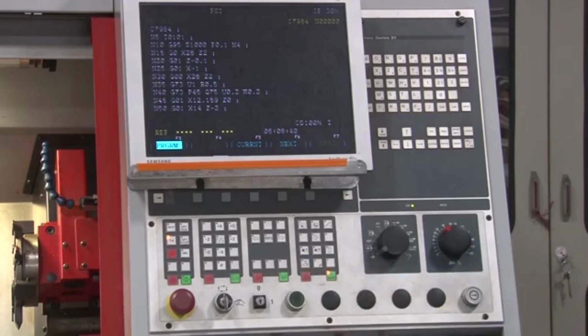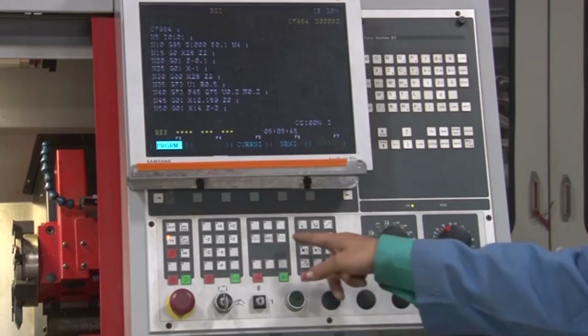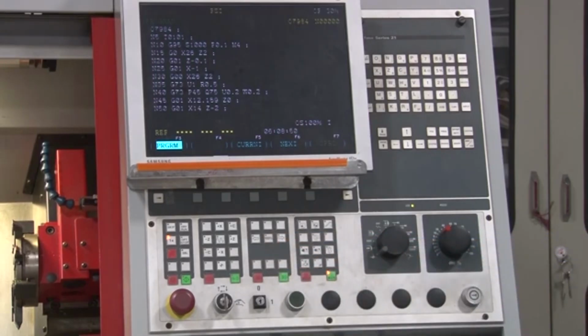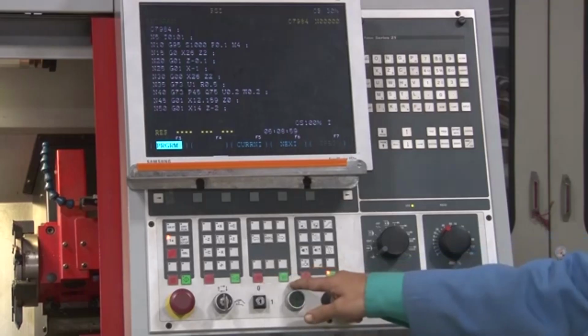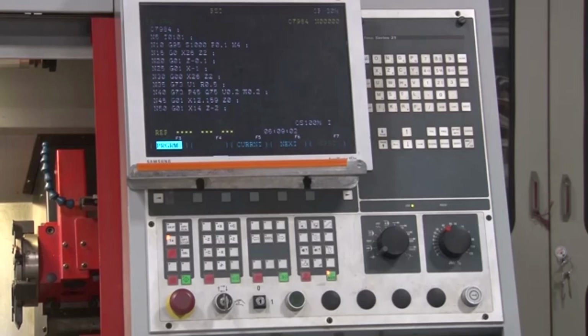Then we have the spindle override, lower, 100%, higher. So, that is done by the knob. Now, there is another one which indicates the spindle stop, spindle start, and the spindle can start in the jog and NC 1 to 1000 mode. Now, what jog is, is that we want to slowly move the spindle, because we do not want the rapid movement, to prevent any accident. So, in that case the jog mode is switched on. It can have the clockwise or it can have the counterclockwise.